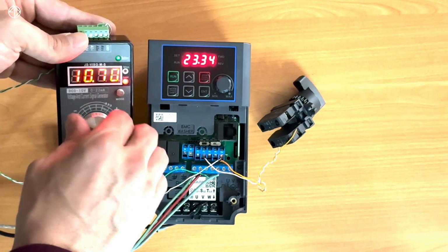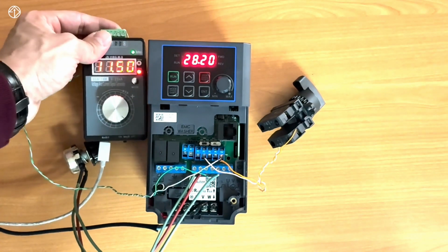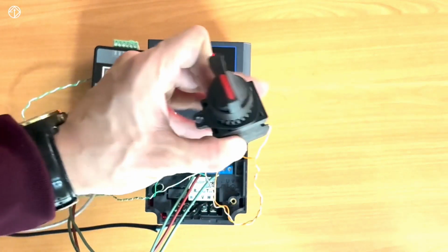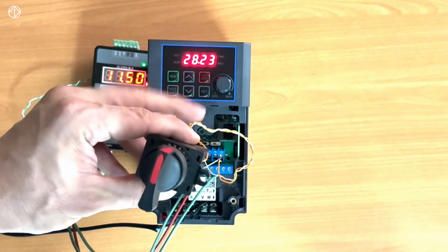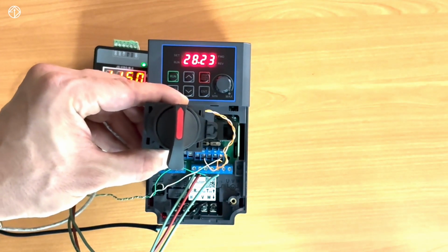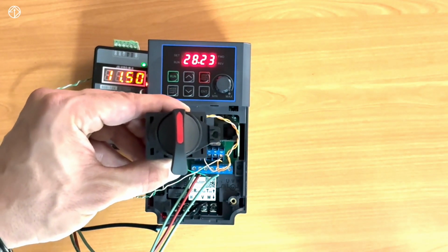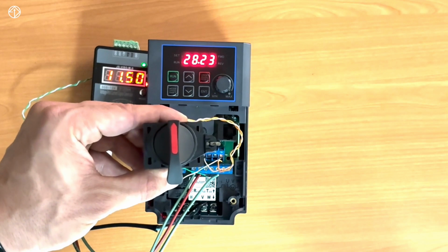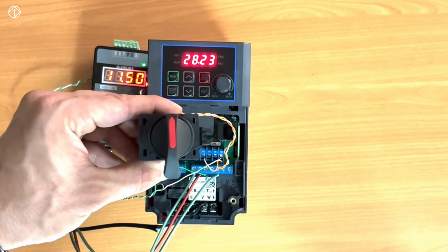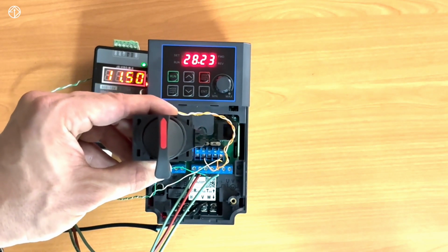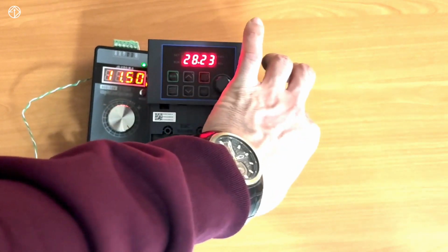So, in this video, we were able to use a digital input, which we had defined as the second source, to activate two frequency references for the inverter. If this digital input was inactive, the frequency would change based on the 0 to 10 volt analog voltage input, and if it was active, it would change via a 2-wire 4 to 20 milliamp sensor.